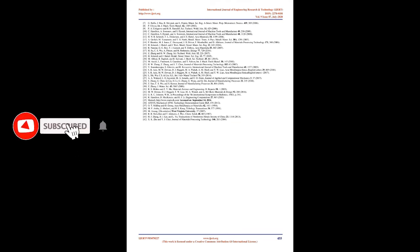The results obtained from this research can be summarized as follows. 1. The temperature field obtained from the FE simulations is in good agreement with the temperature field obtained experimentally through FSW of Alloy 2219. Among the four developed models, the CMFT-WT model produces the closest temperature profile to the experimentally obtained profile.